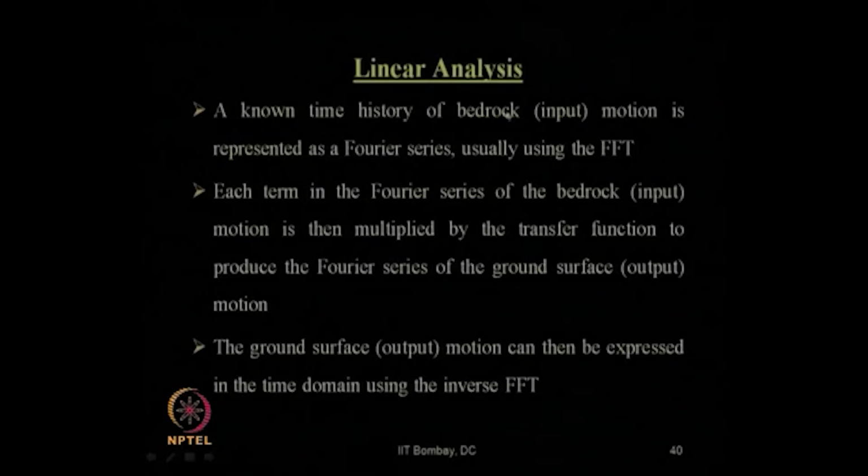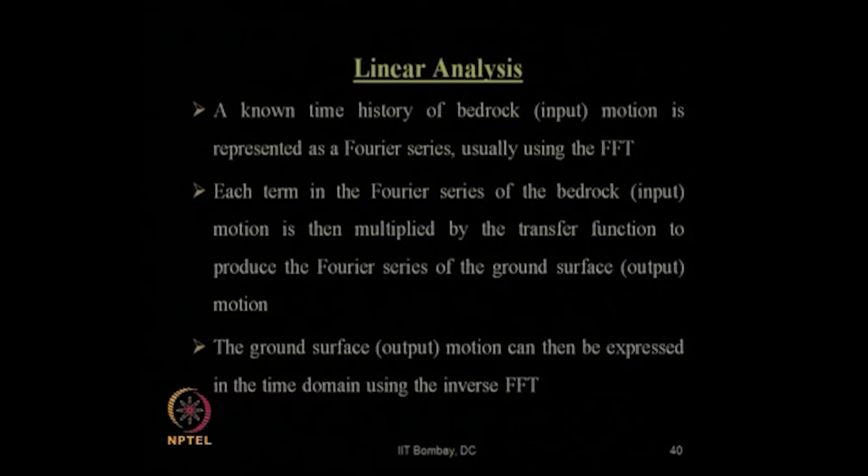Now, in the linear ground response analysis, first a known time history of bedrock motion is considered as an input motion. It is represented as a Fourier series. Let us say it is an acceleration time history, or it can be a displacement versus time history, depending on what you are interested in.